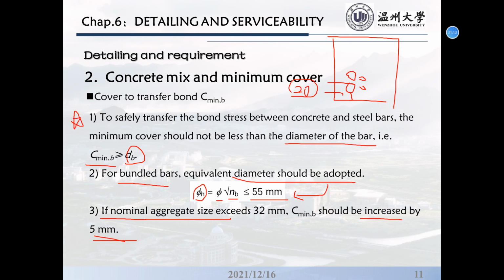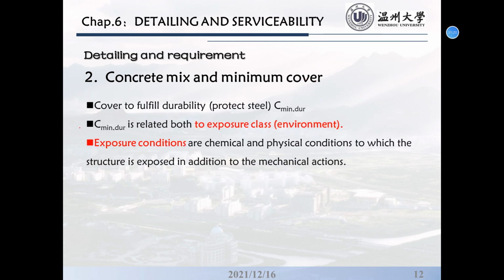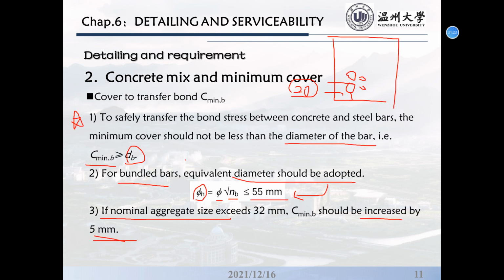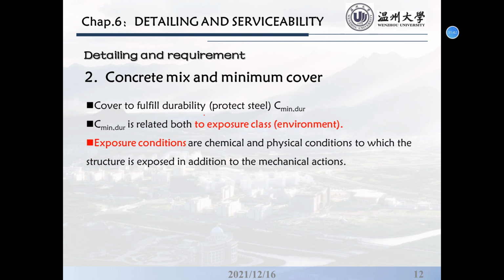Some people may forget, so we just choose the cover easily for the bond. That will cause some problems. Cracks will quickly occur on the structures if you do not have enough cover. Another is durability, which means protecting the steel bars.